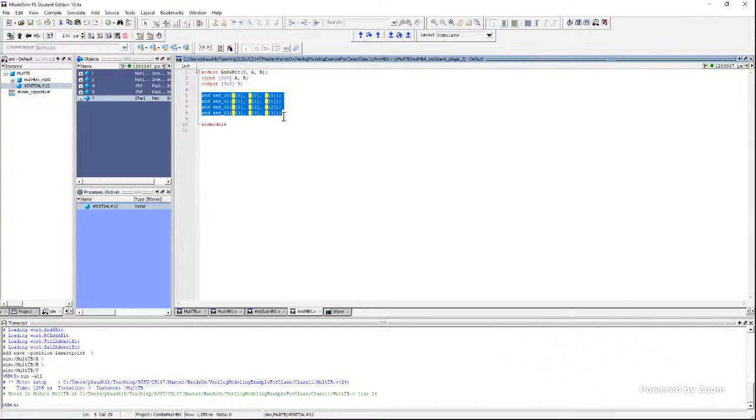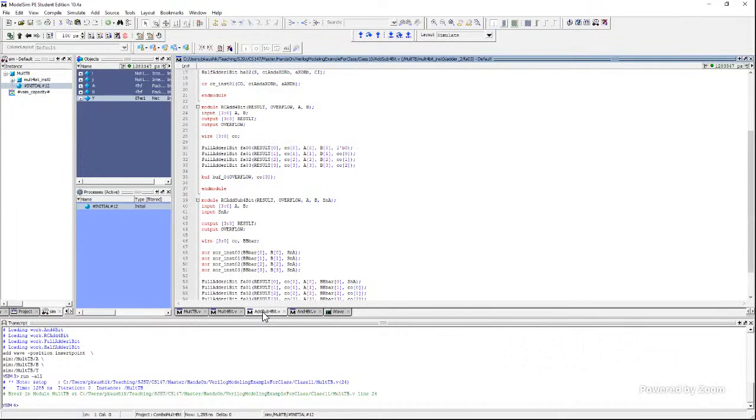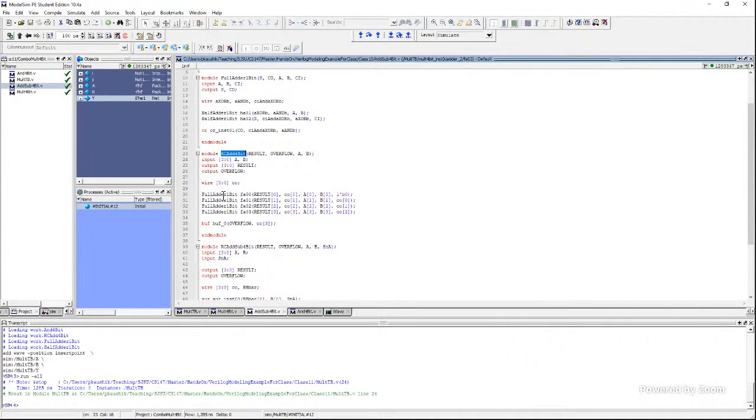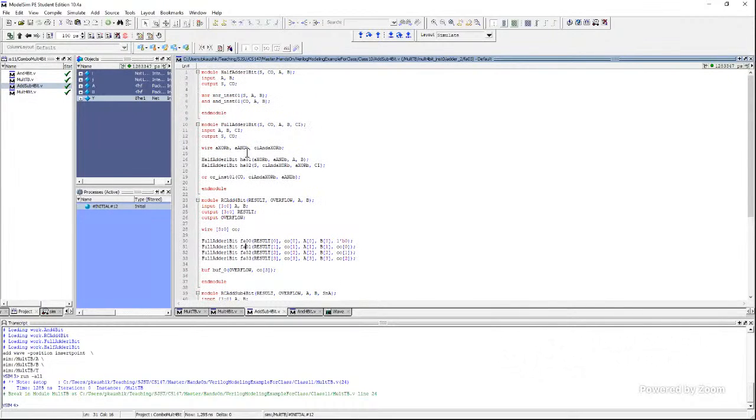And under that AND, you have the basic-level implementation of NAND and NOT. And NAND and NOT, you can do with transistors, right? They're just a bunch of transistors there. And similarly with the adder circuit, if we open that up, a full adder RC, we are combining 4 full adders and a 1-bit full adder. A 1-bit full adder is nothing but some OR and 2 instantiations of half adder. Each half adder is nothing but XOR and AND. And each of them has a physical transistor implementation using NMOS and PMOS.